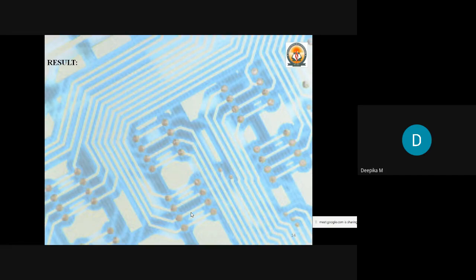Coming to the result, whatever observations we have made, rather than writing in words, we can tabulate our results. That will be very helpful in comparing things. So the performance of all the rectifiers is evaluated and tabulated as shown in the figure, for center tapped and for the bridge type. What about the ripple factor, percentage efficiency and percentage regulation?